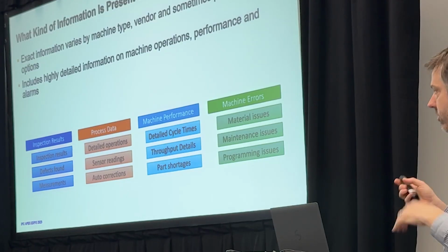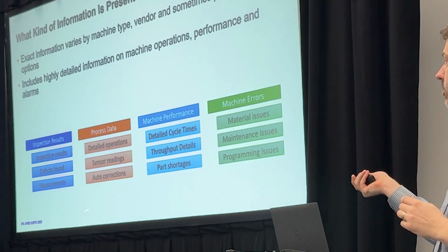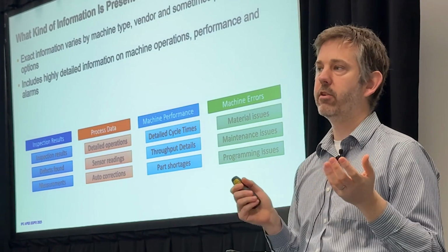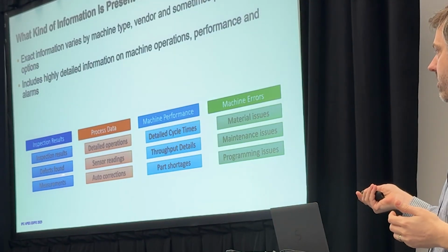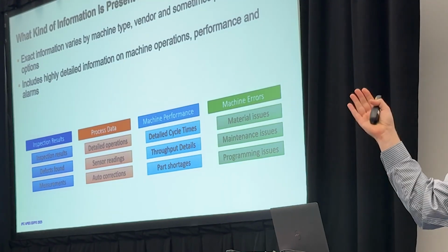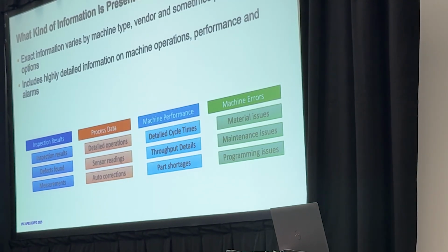And then this is supported by a number of measurements, often many more measurements than the ultimate pass or fail. And these measurements can be super valuable on their own, even for units that ultimately passed. So for example, an SPI machine might make 5,000 or 6,000 measurements or more on a large PCB, ultimately to find 0 defects and everything passed. But those 5,000 measurements, if you analyze them in the right way, could tell you a lot about the health of the solder paste stencil. For example, it could tell you I was starting to get a clog on one of the apertures. Hasn't been a problem yet, or maybe someone decided to set the bounds really wide on that process so everything passes. But still, you put the machine there for a reason. Might as well look at what it's doing and see if it can tell you something of value.